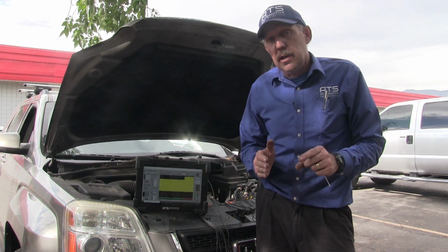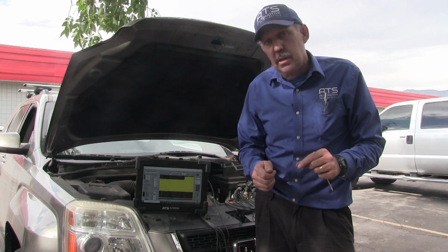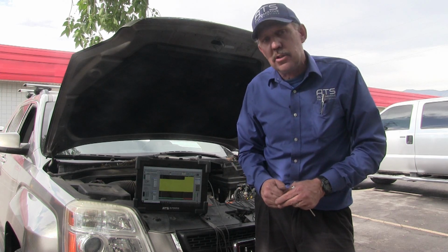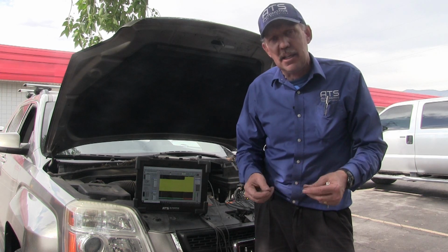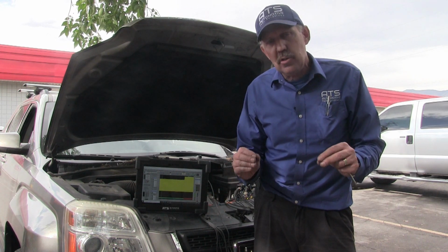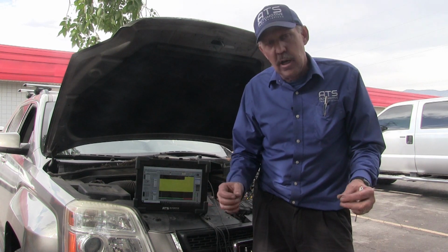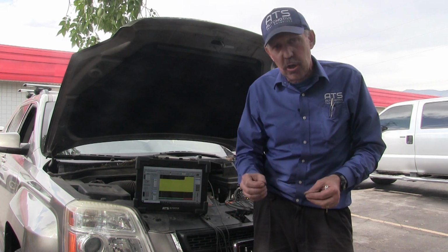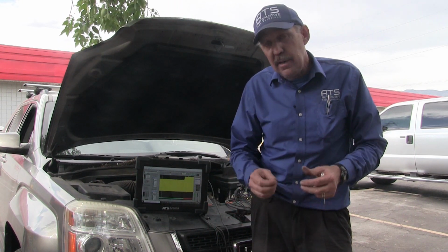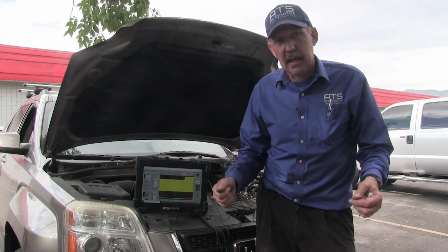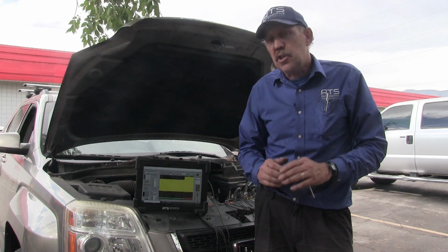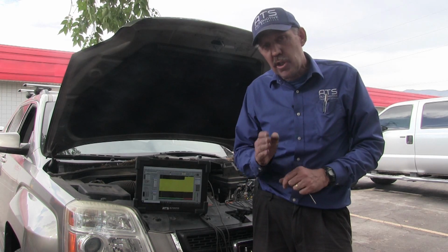But what I really want you to understand is by using sensor simulators, you have a huge gain in your diagnostic strategies, because I can test for a circuit being loaded without ever disconnecting anything. As soon as you disconnect things, things can change. So whenever you disconnect something, make sure that you know why you're disconnecting it and what you're expecting the outcome to do. Many shops I go to, they just start disconnecting connectors, and then that sets up defaults within the system and they get confused. Don't be confused. Stay on target.